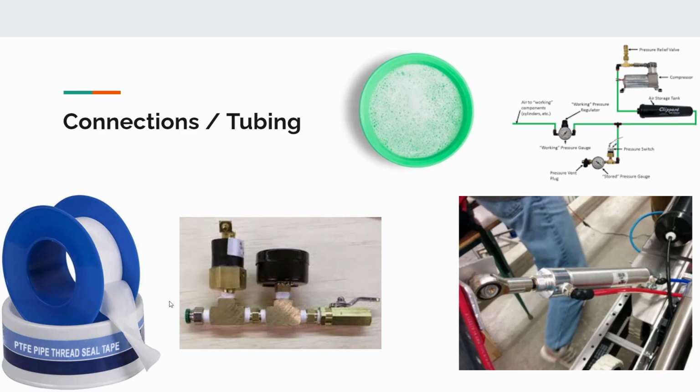Once you have cut your tube to the desired length and it is as flat as possible, all you have to do to connect it is just push it in. To disconnect, pull up on that green circle, and while you are pulling up, pull out the tube.